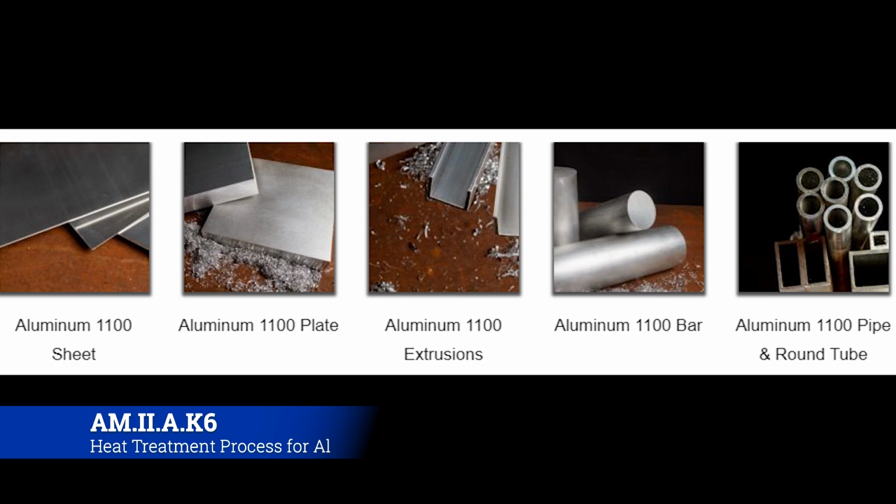But you can also get plate aluminum. But obviously plates are plates. They're thick, heavy pieces of aluminum, so it goes without saying that we don't use that much of it. But there are places where you might see aluminum plates being used. Extrusions. There is definitely a place for extrusions on the aircraft and different structures, depending on what aircraft you're working on. That'll be the case.